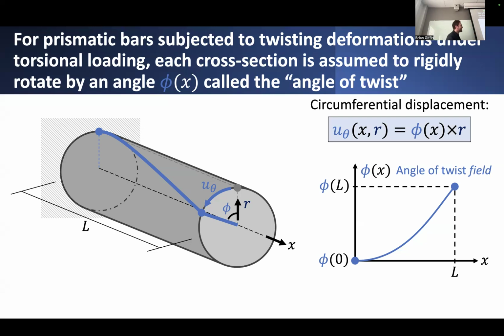So that is to say that if I were to cut through this cylinder, or maybe just consider the end cap of this cylinder, I can envision what happens to that end of this cylinder under torsional deformation by assuming that it undergoes a purely rigid rotation, but not a rotation about either of the transverse axes. In this case, it's a rotation about the actual axis of this shaft itself.